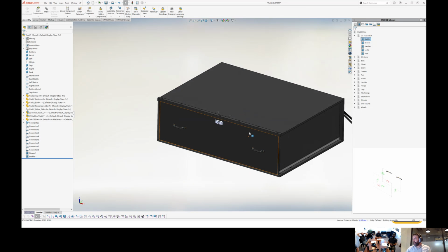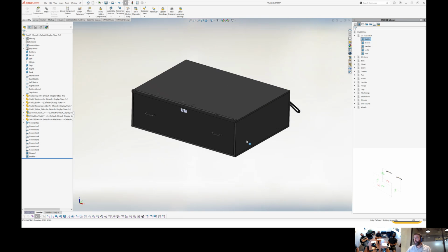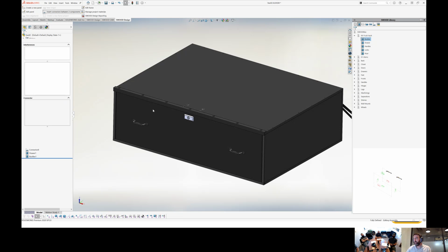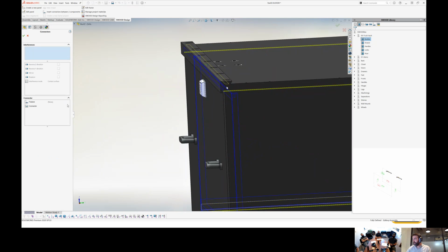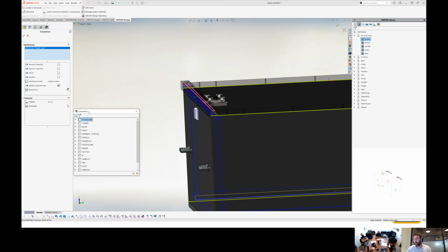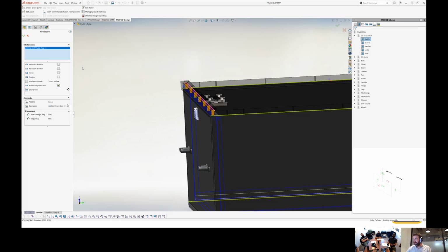But what I want to show you is that even with parts that are not inserted, like we have seen with the SWOOD feature, I still have the option to insert my connectors. So for example, I can here again just detect the contact faces between these two, and we'll just insert my drill, just like that.